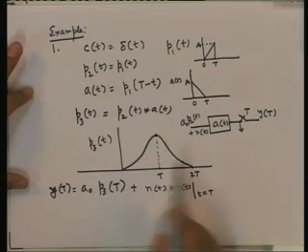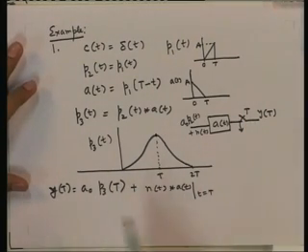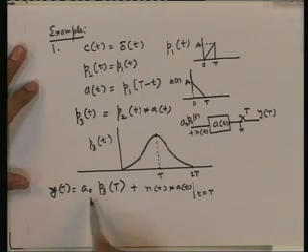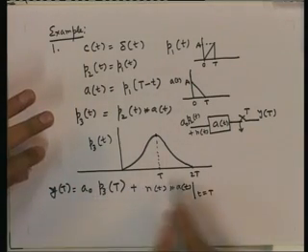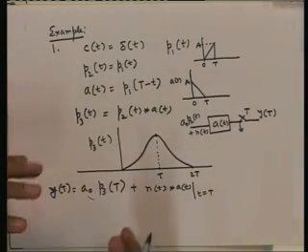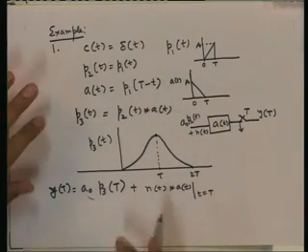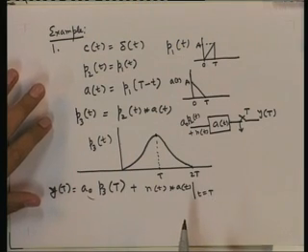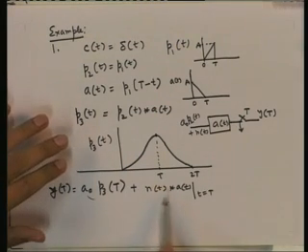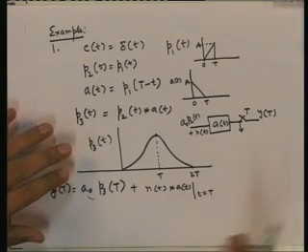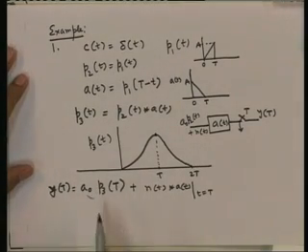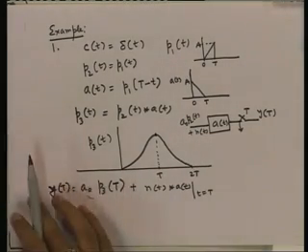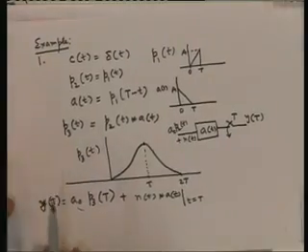So, this is sampled at capital T or multiples of capital T, because we want to amplify the signal part of the received signal as much as possible. We are multiplying A naught by the maximum value by sampling at capital T, because the noise variance doesn't vary with sampling time. So, we have seen in this example why we sample at capital T when you use the matched filter as the receiver filter.